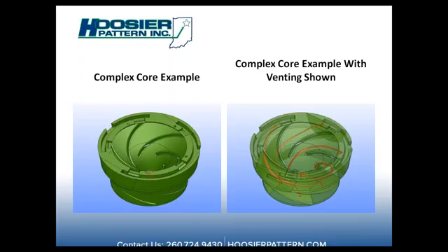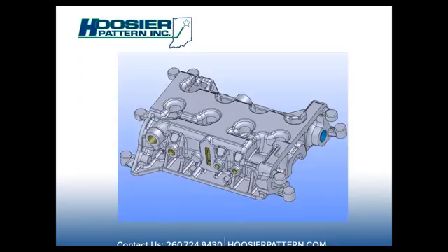If you're requiring a mold package, you have multiple options as well. First thing to remember is that you don't have a specific flask size. Print your mold to fit what you need. No bigger, no less. The printed sand is somewhat expensive compared to molded sand, so use it wisely.